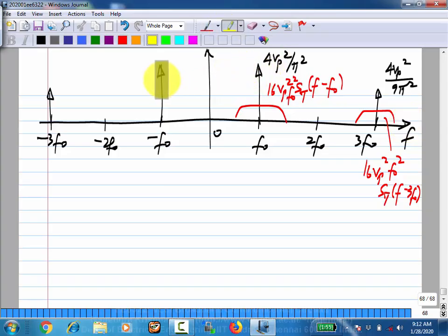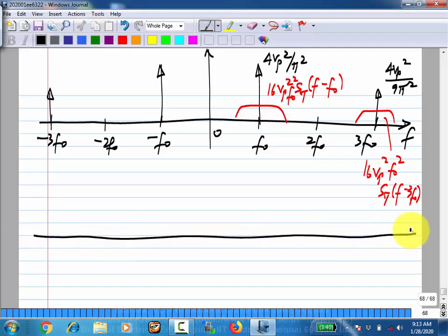So essentially the square wave will have impulses at odd harmonics of the fundamental frequency, and then this jitter will have some sort of a spectrum around each of those harmonics. Is this okay? Now the interesting thing is that, let's say I look at this part, you can take any one of them, you will get the same result. Look at this part, and I normalize this to the strength of the tone itself.